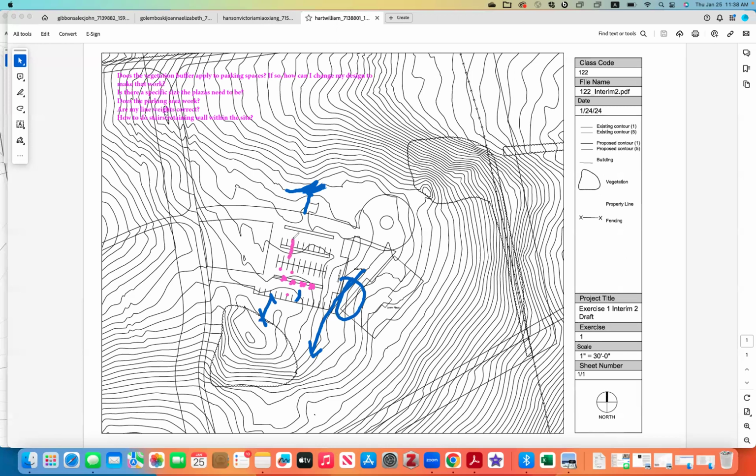You would measure 25, and then you would have your parking stalls over here. And then you close it off, you know, for it to come in like this. Well, you want to come in where your driving aisle starts. You align, okay? Basically, suppose this is the actual parking stalls, your road flows into the driving aisle and then comes back and loops around.